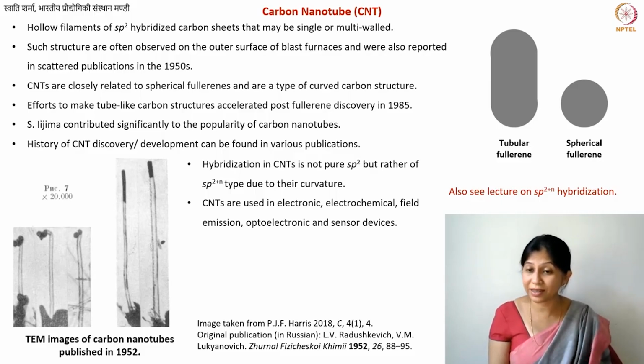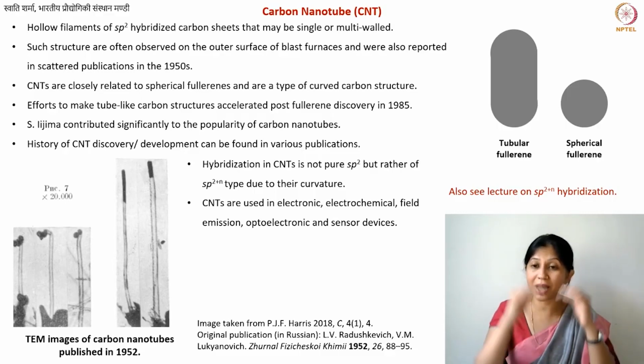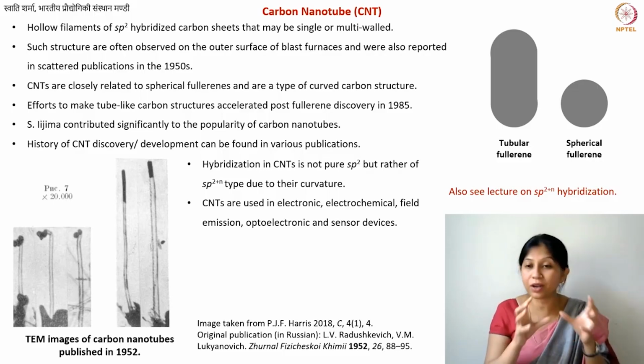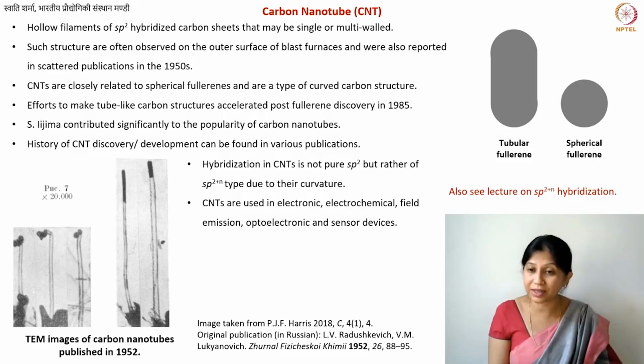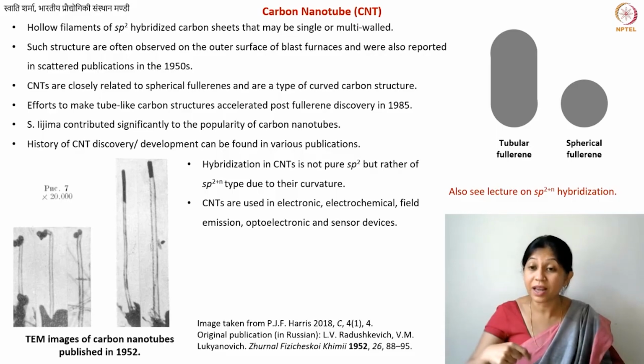But that is not the case with carbon nanotubes, because in most cases, carbon nanotubes are prepared by bottom-up processes. This is an atom-by-atom deposition. Or if not atom by atom, at least it is smaller units coming together, so it is a bottom-up process. And in the case of bottom-up processes, the defects are much, much less. And especially when you have extremely thin walls, whether it is single or multi-walled carbon nanotubes, you have very thin walls of these tubes. There, it is not even possible for very large defects to exist.